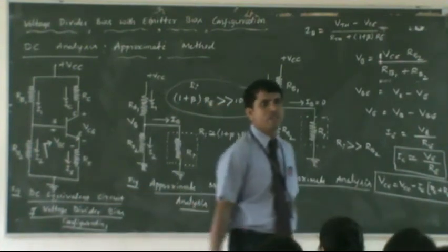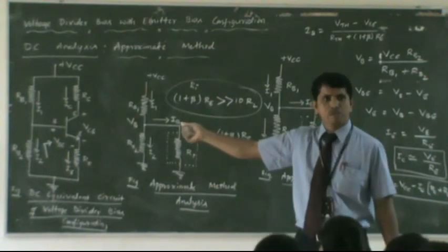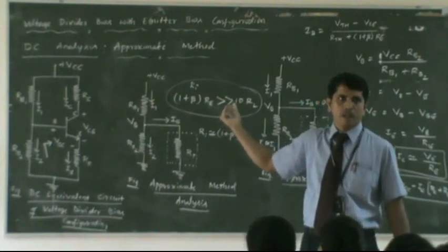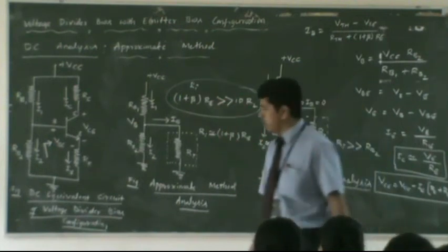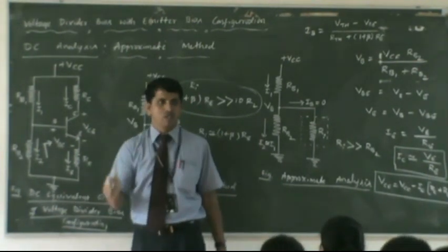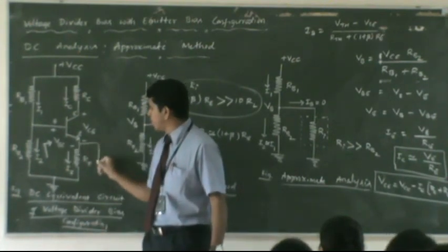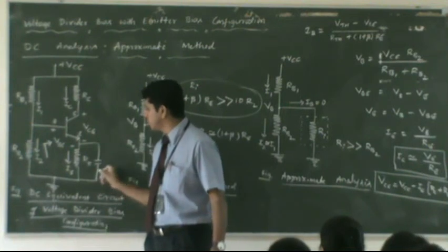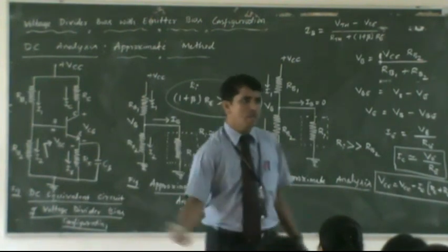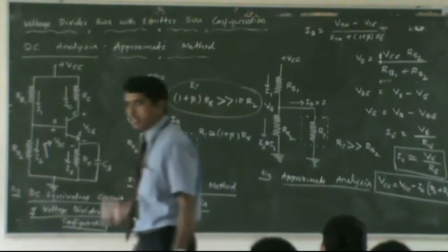If I ask you to create a common emitter amplifier for laboratory purposes, what you can do is take the same circuit and add two capacitors, one on the input side and the other on the output side, along with AC sources. Many people have made modifications to this, but the total circuit has not changed. Only small modifications have been made. Especially, they have started including a capacitor here, called a bypass capacitor, CE. Adding a capacitor there, look at whether the DC analysis will change.